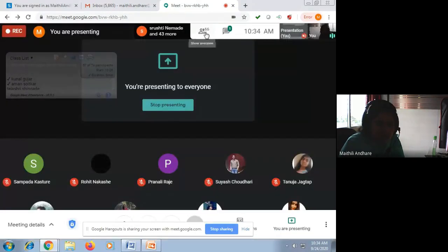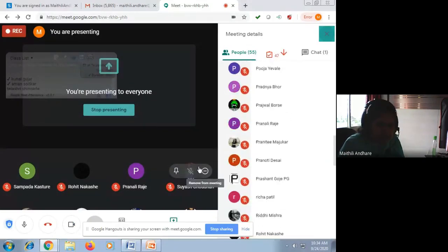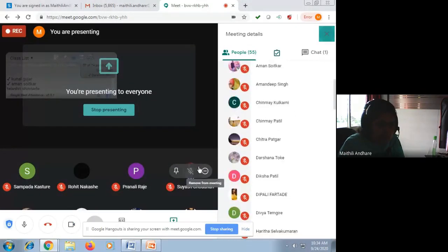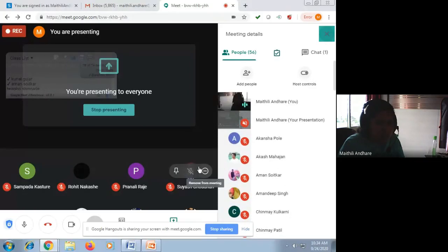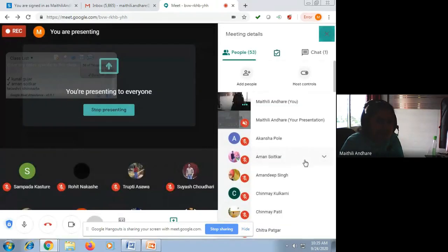I have given the logic also, what should be the flow of the program as it is timer 1 and mode 2. What is the size of timer in mode 2? That we have discussed in the previous lecture. What should be the value range of the value to be loaded in the timer register? 0 to FF. Why? Because it is an 8-bit timer in mode 2.